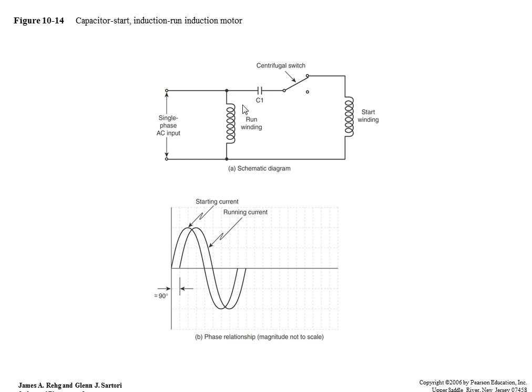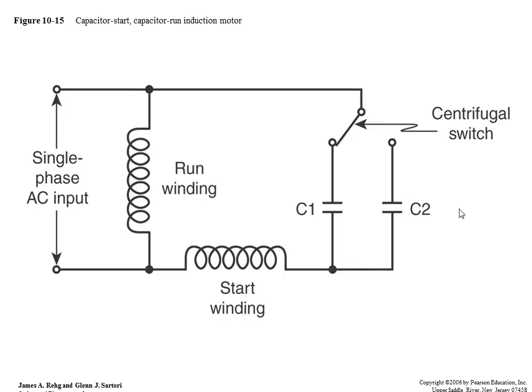We can also throw in a capacitor. So this is a capacitive start guy. It's got a starting winding and a capacitor that has to charge, and there's going to be a change between the starting current and the running current. Those capacitors are bigger than my fist in general, a little bit longer. They sit on top of the motor. Last a long time, but they may have to be replaced. So that would be something that you could do. Units, outside compressors have them. Yeah, exactly.